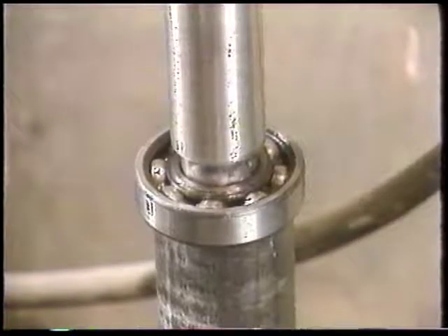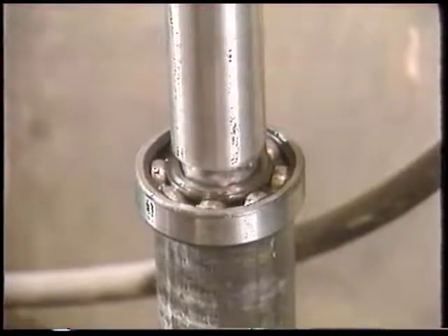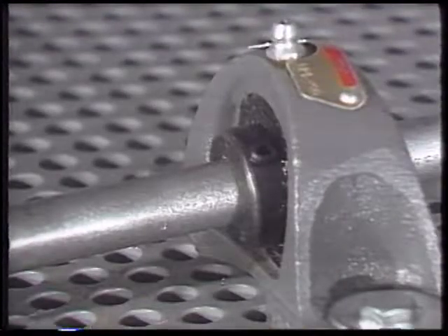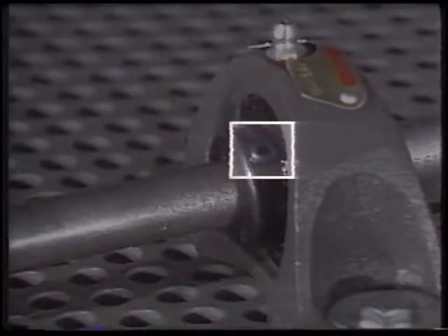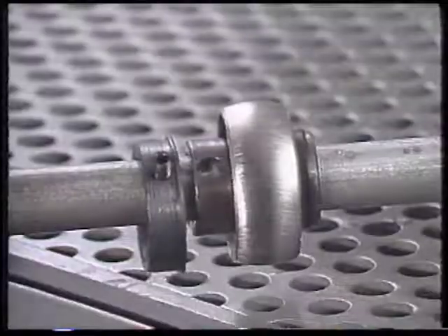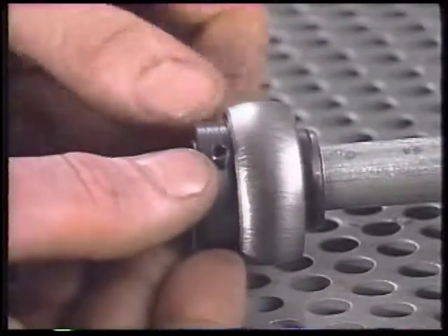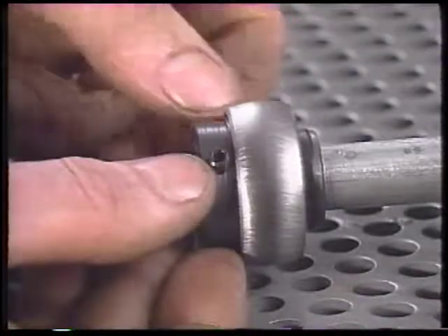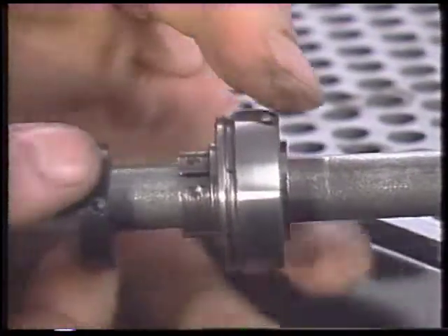When the load and a bearing ring move together, the fit must be considerably tighter, or the ring will creep around on the shaft or in the bore. Inner rings are often locked mechanically. A common method is the use of set screws connecting through an extension of the inner ring. There are various kinds of locking collars. In some, the set screws go through the inner ring to the shaft. In others, a clamp squeezes the bearing's inner ring tight on the shaft.